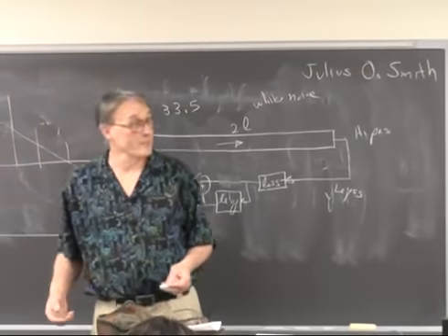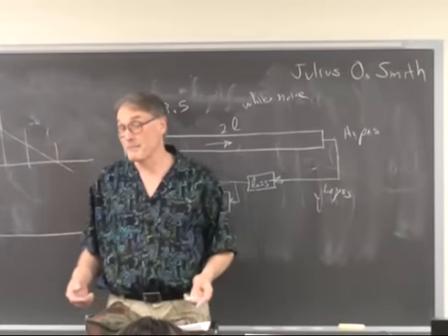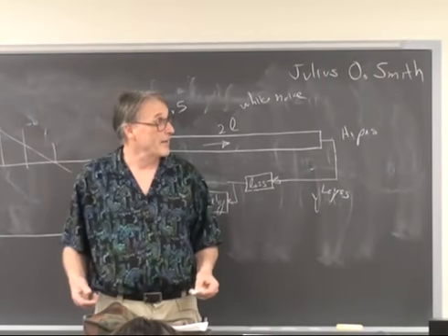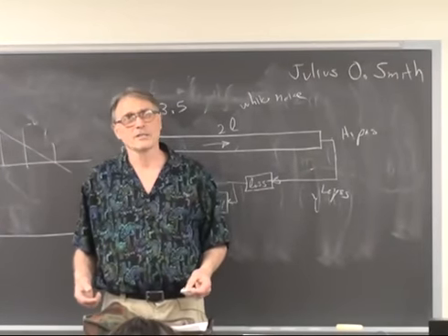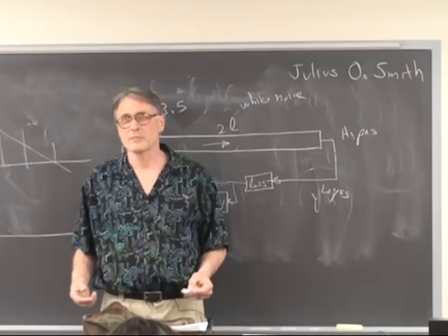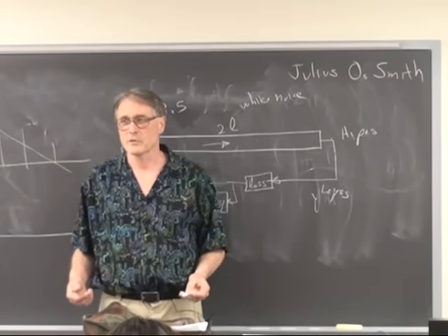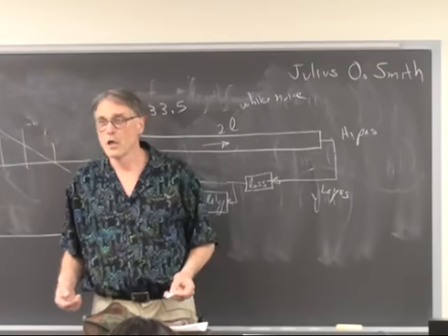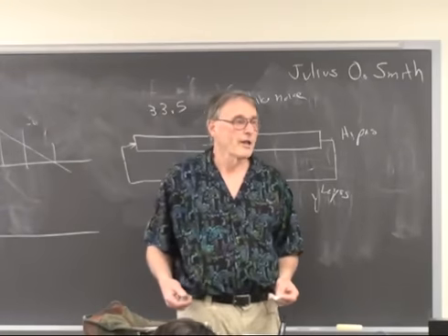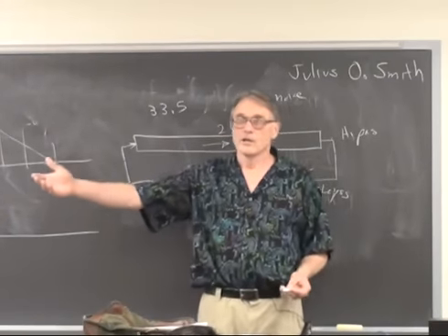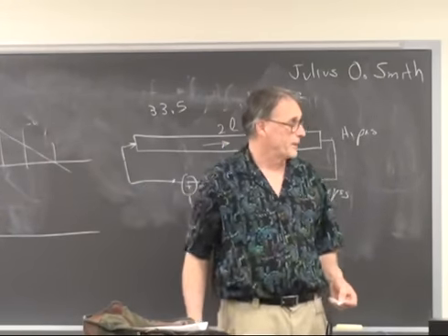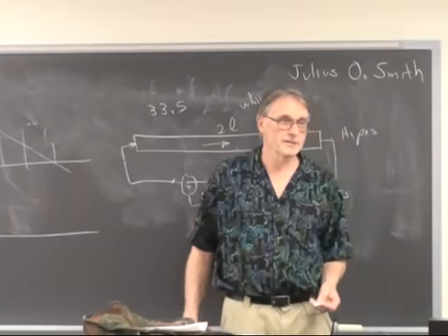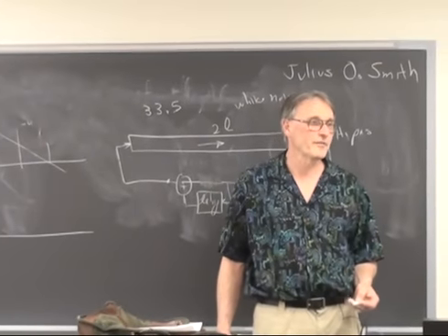I wrote a 127-bit random number generator for a very demanding simulation. And then I calculated, well, I'm running the simulation at 50 megahertz, generating 6 numbers. How long will it take to repeat? Never. Effectively, never. Entropy will kill the galaxy before it repeats. That's a good definition of never.